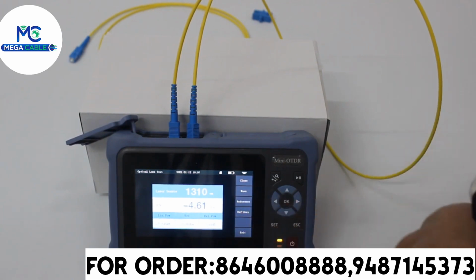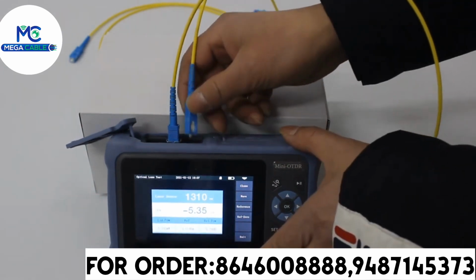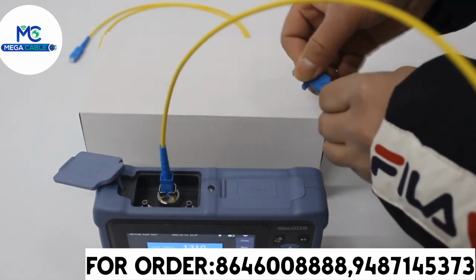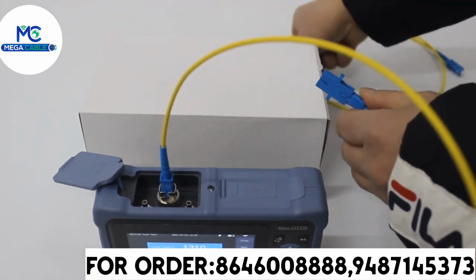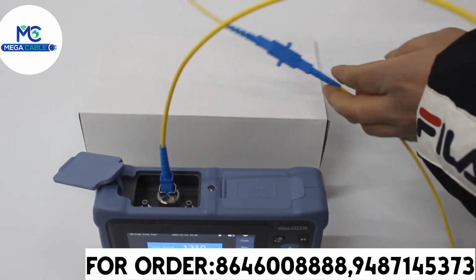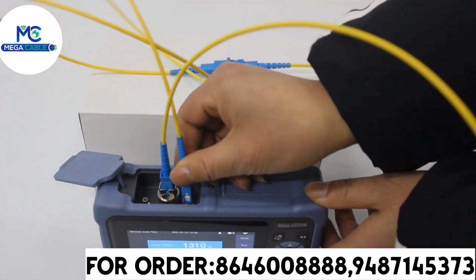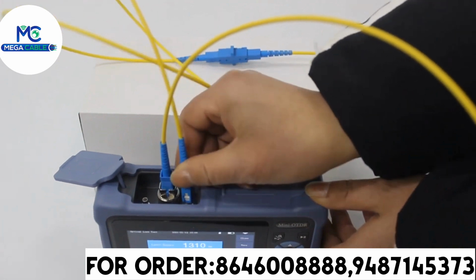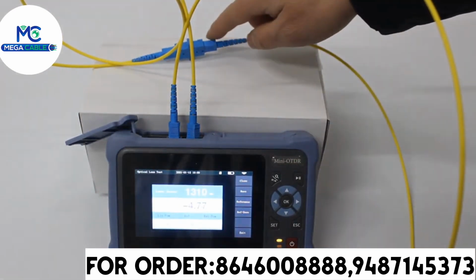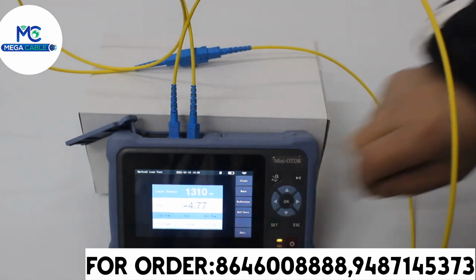Click Reference to set reference value. Take out SC connector from OPM port and connect with SC adapter and the patch cord on the test. Connect the other side of patch cord on test with OPM port. The insertion loss of this connector is 0.15 dB.